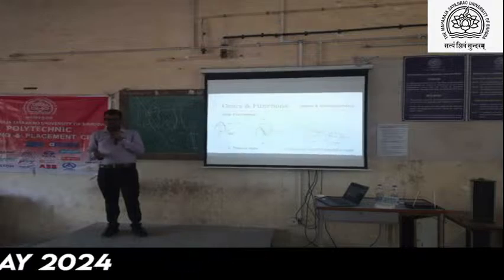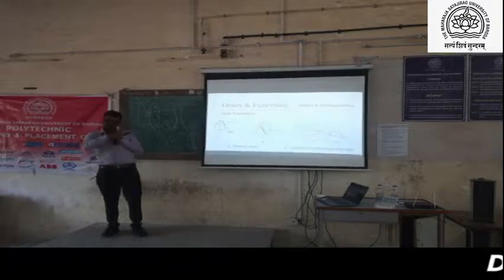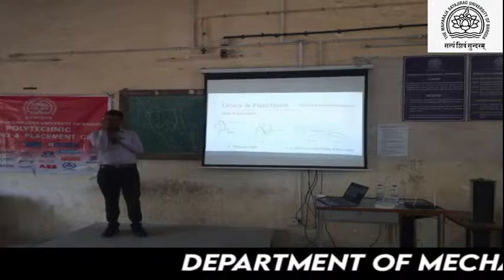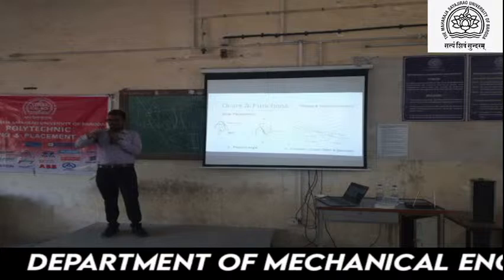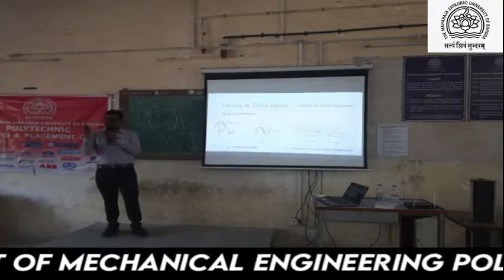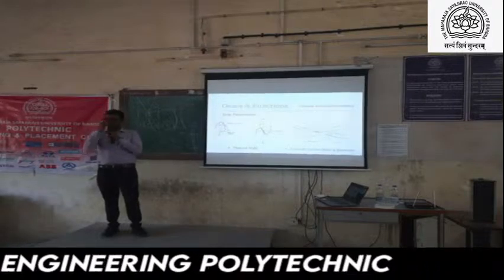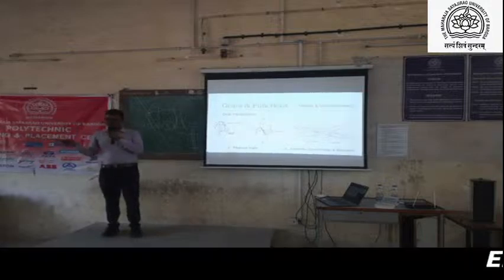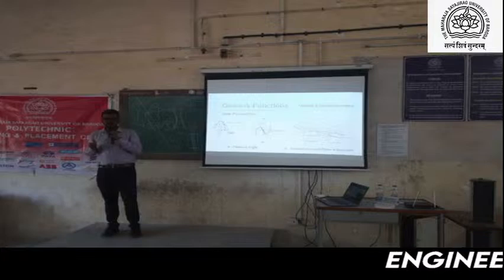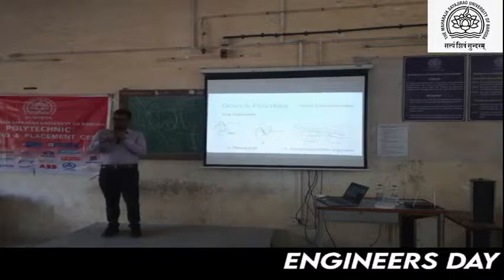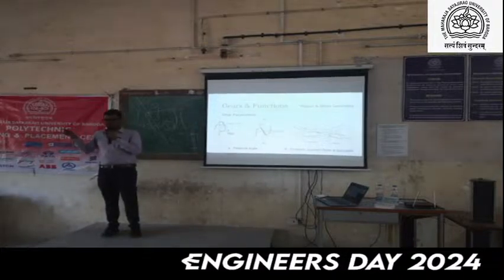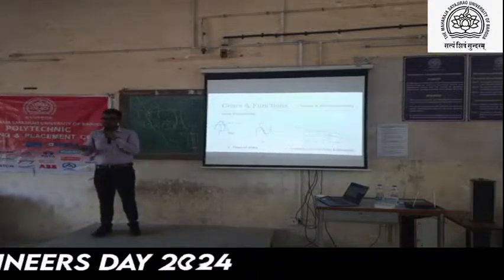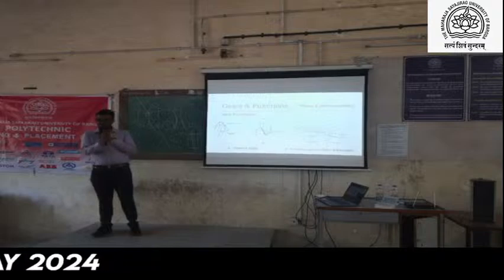It is having some angle alignment. Spur is at 90 degrees, helical is at some tilt. That tilt is increasing your contact, so that tilt is considered as overlap. So transverse contact ratio plus overlap ratio is the total contact ratio. Can you get my point? So in spur, the overlap ratio will be 0, so the total contact ratio is the transverse contact ratio. In helical, it will have some value.